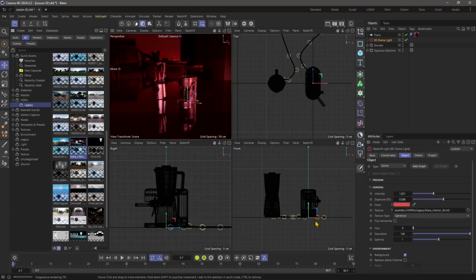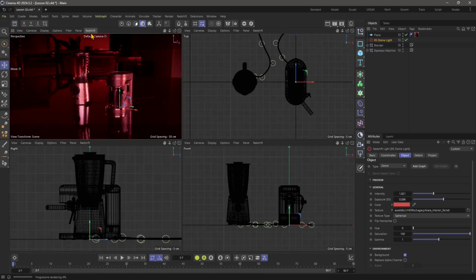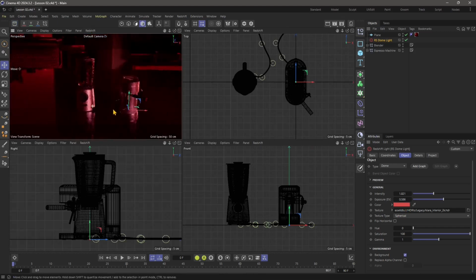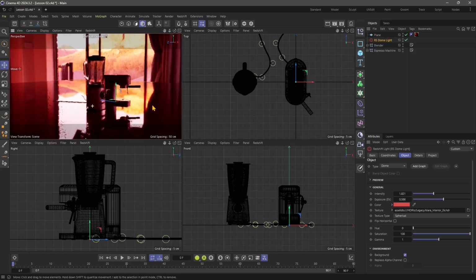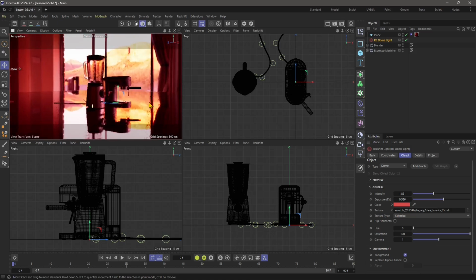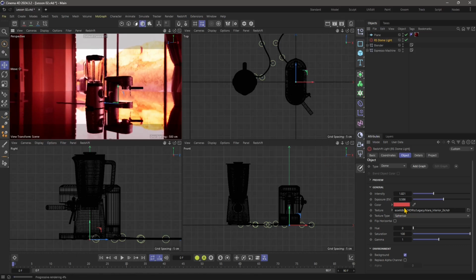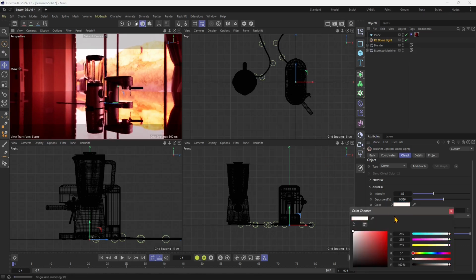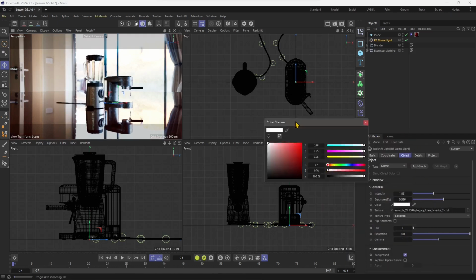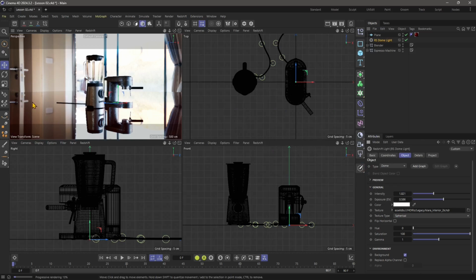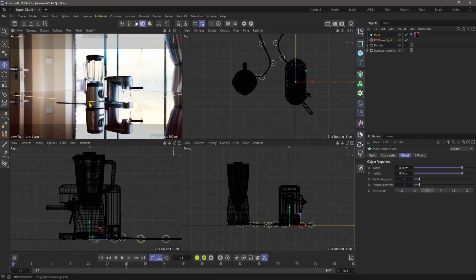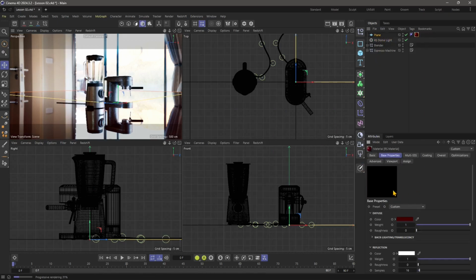You're gonna see the results, and you can immediately see that the rendering is going to be way more accurate and realistic than the previous one, because we're not using a simple color anymore. We're using an entire image, which is going to affect the reflections and is going to affect the lighting system. And also want to change here from red to white. As you can see, you can also give a tint to your HDRI image-based lighting. Now, this is again a technique that is used in every rendering, and it's called image-based lighting. So you can set up the reflections, lighting, and the background.